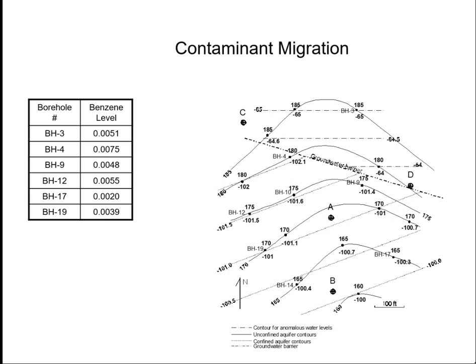So a question about this might be, describe the ground surface, or where would water be inclined to flow at the ground surface here? Obviously that's going to be straight down the middle if it's following the topography, because we have a little bit of a valley down the middle in the groundwater, which mimics the surface. And then we've got all these straight lines that are confined aquifers, and there are two of those that are divided by a groundwater barrier.